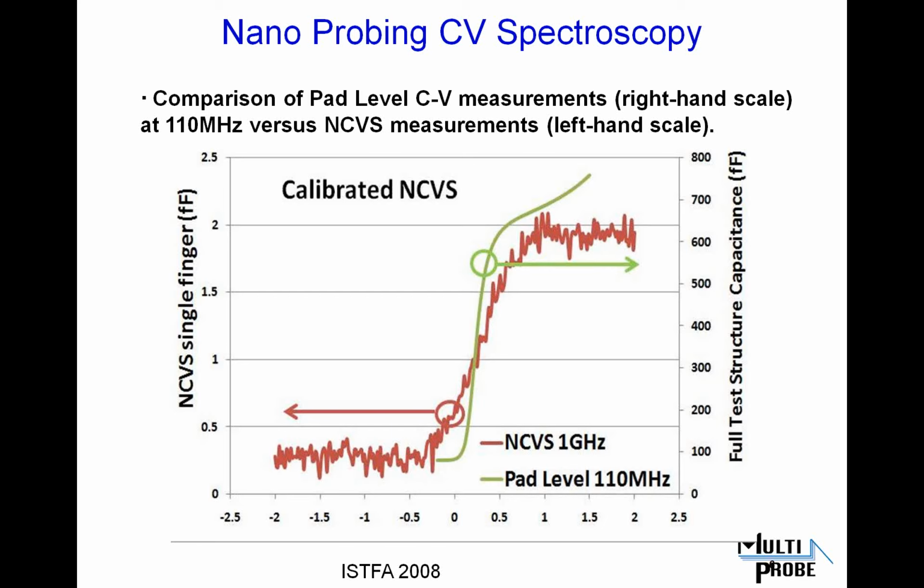So there's some errors there in that box, and the reason why the gigahertz sensor isn't susceptible to that is that it is a resonant sensor instead of a bridge. The resonant sensor isn't loaded down with a little bit of gate leakage. It doesn't really care. It just passes through the sensor to ground, and so it doesn't really bother it that there's some gate leakage as you accumulate the gate oxide.